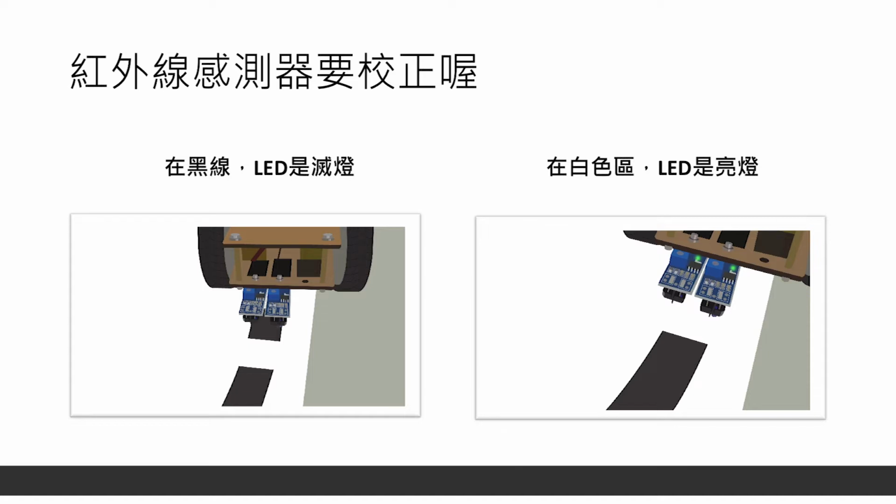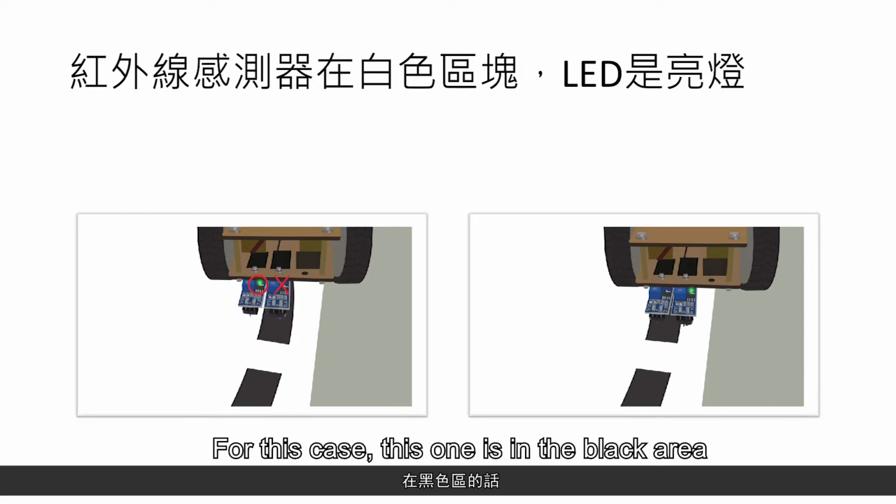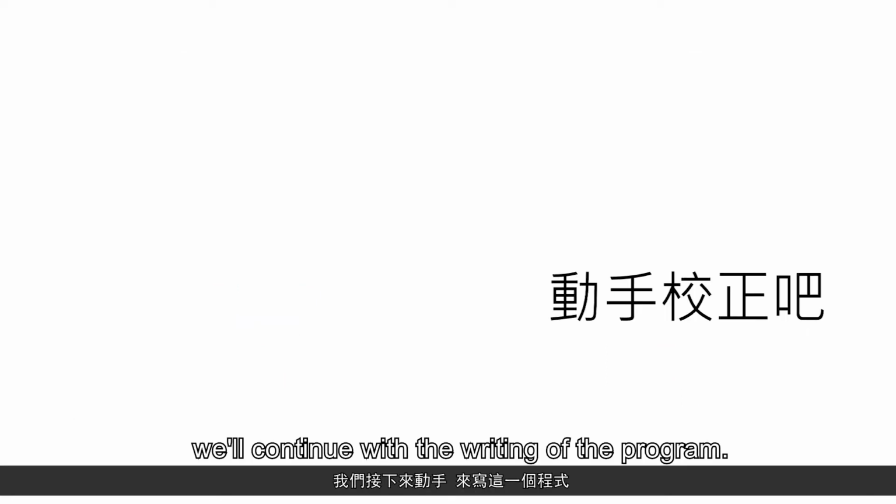Let's take a look at this. When it's in the black area, the LEDs of both sensors are turned off. If it's in the white area, both LEDs are lit up, so there should be green lights showing. The same goes for this. If it's in the white area, this will show a green light, and this other one doesn't. For this case, this one is in the black area, so it doesn't show the green light, and this one in the white area shows it. You can check this first. And if all is fine, we'll continue with the writing of the program.